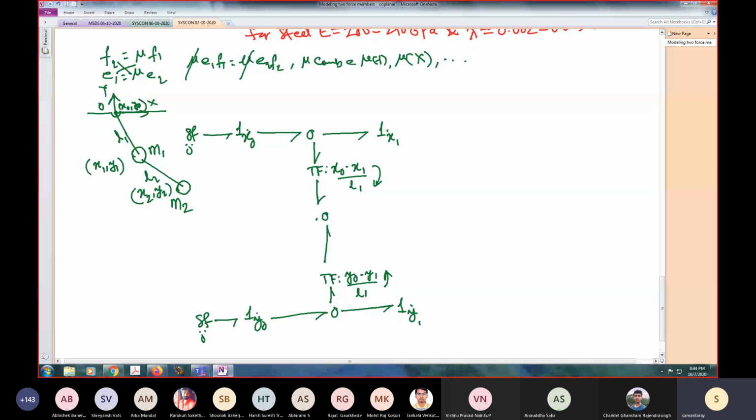Add them up, first pendulum stiffness and damping. That pendulum rod's stiffness and damping, C is, let's say area is the same, Young's modulus is the same, AE by L1, and lambda times AE by L1. So this is the first pendulum model. Now the second pendulum is a first pendulum like thing, but its base is moving. The second pendulum is hanging from the first pendulum. So it's an exactly repeated model.